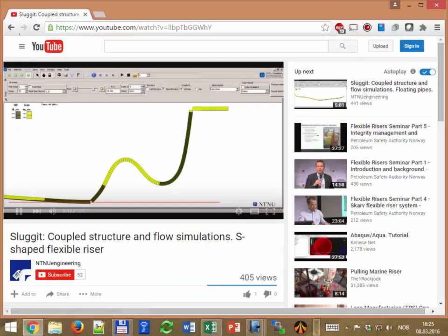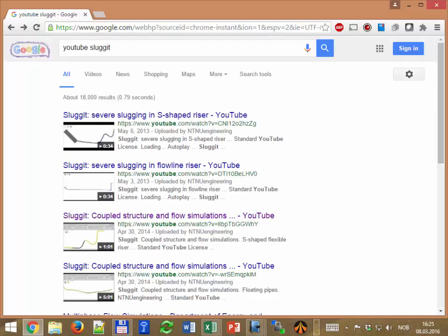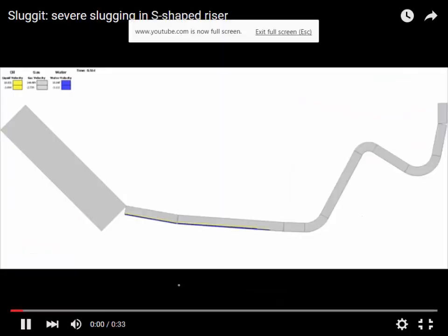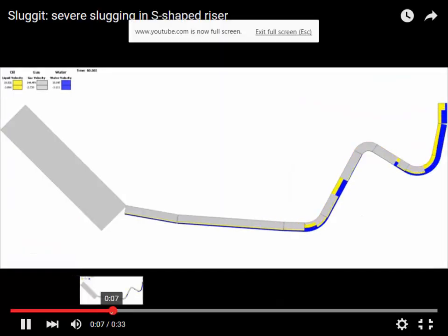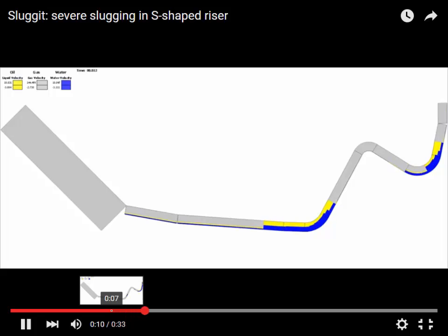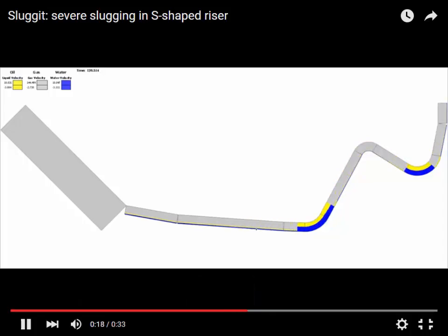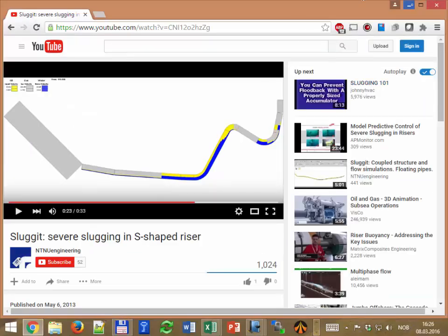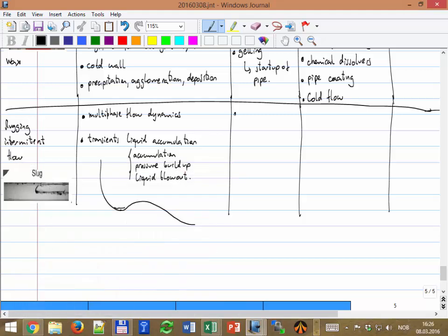And there are also quite a lot of other nice videos that you can take a look at. So you have liquid accumulation, pressure buildup, and then you have kind of a blow by where the gas comes in a plug and actually flushes everything that is in the system. So problems that we can get because of that is unstable operation. Remember, we don't like that too much for the processing facilities, separators.